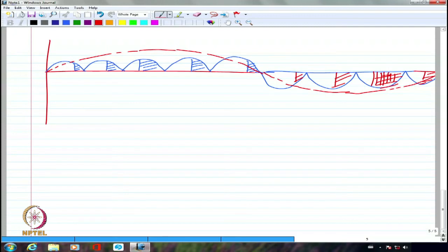So I am calculating the area under the curve, which is actually 3 Vm by pi cos alpha normally, and then correspondingly I am looking at not 3 Vm, but 2 Vm by pi for single phase. We are still talking about single phase. So I have to calculate for that and then make sure that the firing angle is adjusted accordingly.